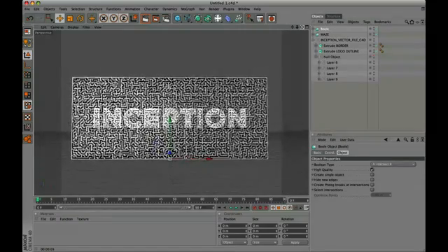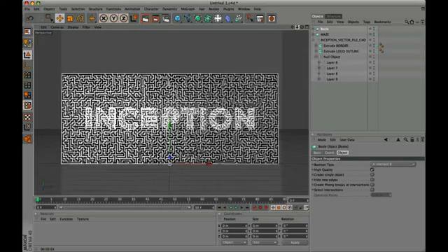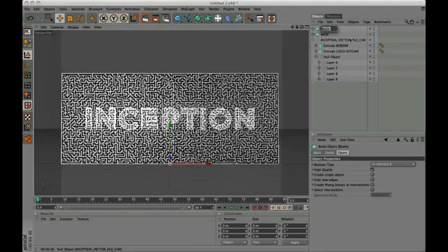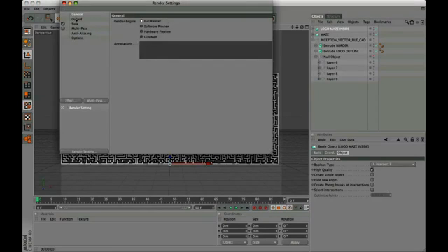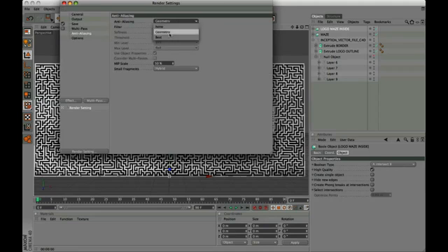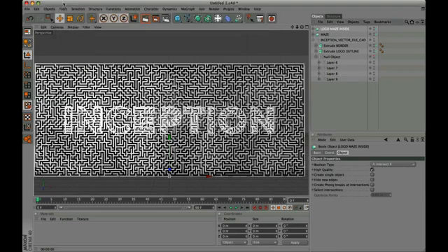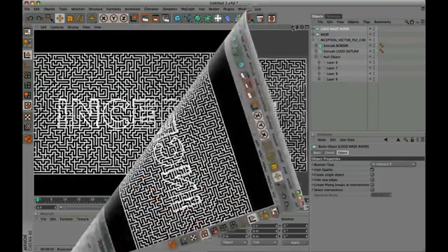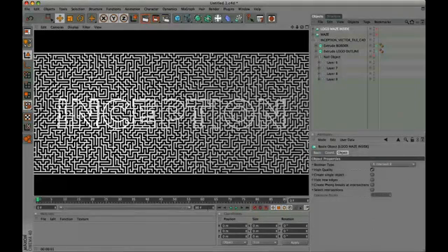We set the perspective view to front view. Rename the object created Logo Maze Inside. Go to the render settings panel, and we set two parameters of our scene: 1920 width, and height to 800. The final frame to 240. Best on anti-aliasing, and return to our project. We set the timeline to 240 frames.